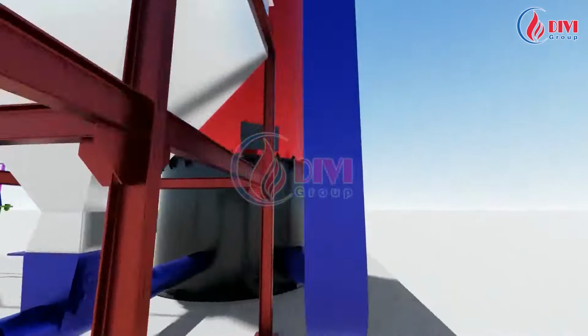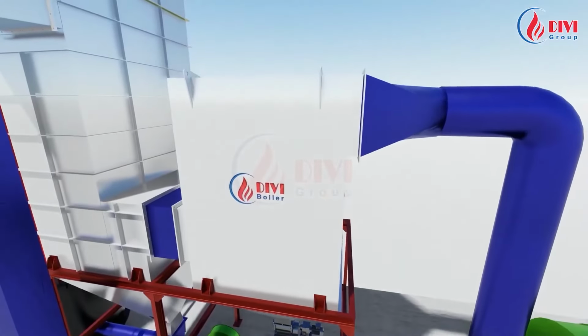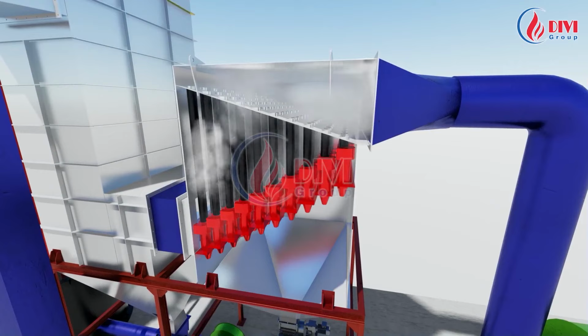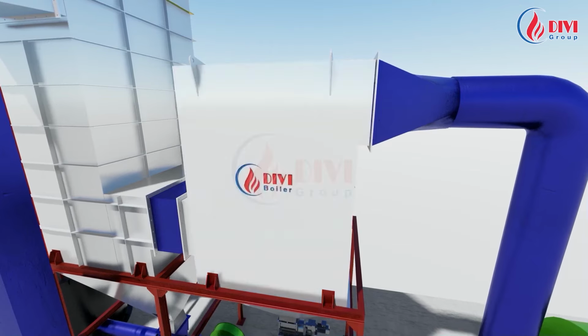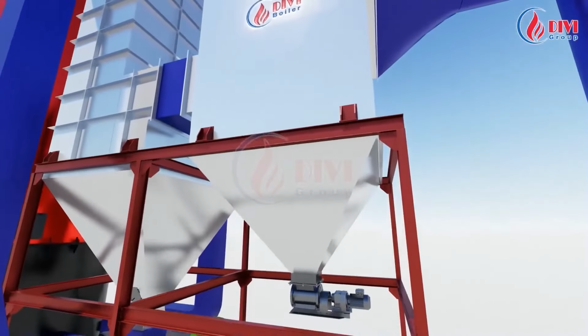After the smoke stream is fully utilized for heat, it is put into the dust multi-cyclone filtration system to recover most of the ash particles present in the exhaust smoke. The dust multi-cyclone filtration set includes many centrifugal dust settling elements designed according to British standards. The recovered ash falling into the lower hopper will be taken out by means of a rotating valve.